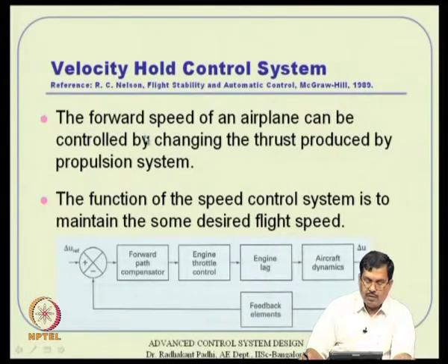What do you do? Obviously, in any type of control system, and these are all based on PID ideas, you have some sort of reference command, that means that is the speed you want to maintain, and your actual speed can be something different. So, you give the throttle command as some constant gain times the error in the output. That is the P part: if you really want to talk about PID control, then P control is K times E basically, or minus K times E, depending on that. So, you know that this output, this delta U, that means the error in the speed, is actually a function of the error in the reference command and things like that, which is typically compensated by engine throttle control ultimately.